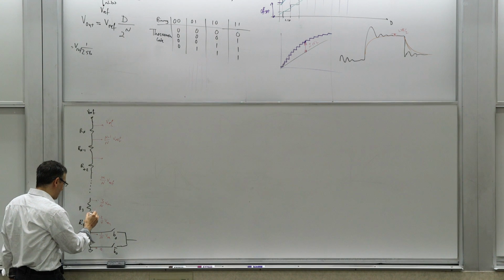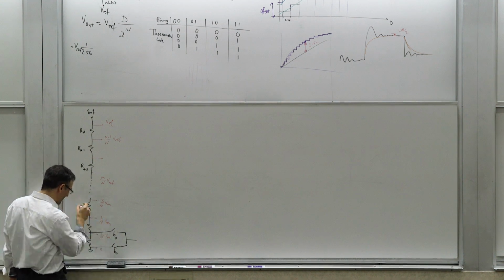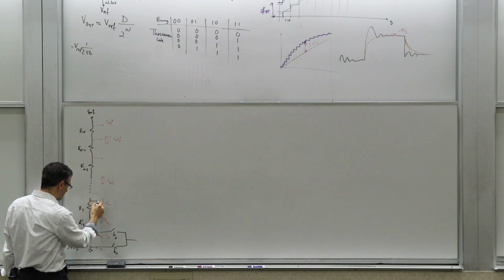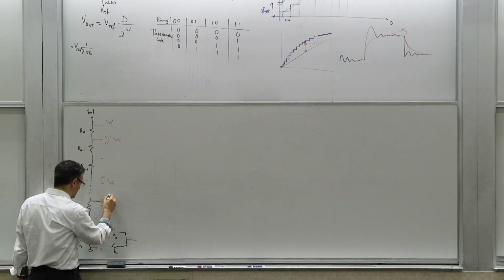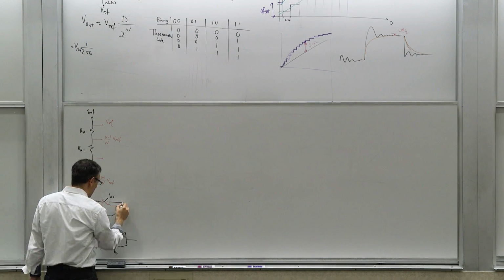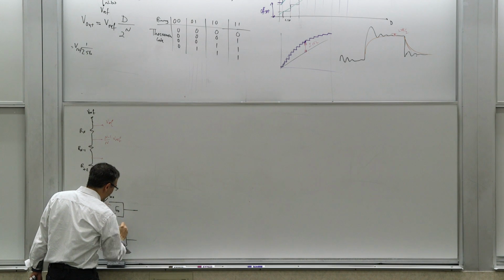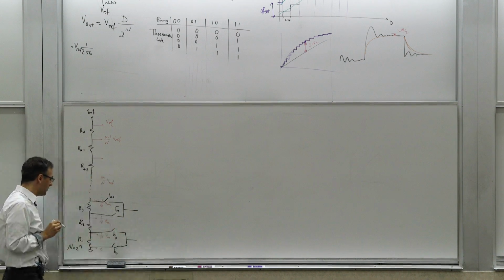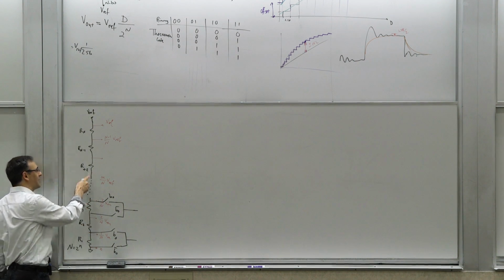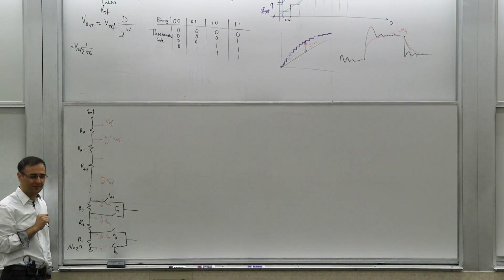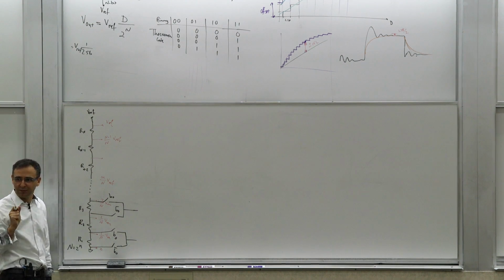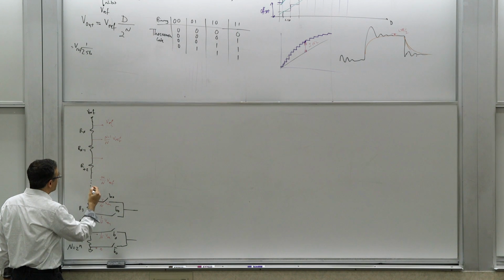Right? And we repeat doing this every other stage. B0, B1, it's going to be B0 bar. Because you remember, if the LSB, the lowest bit, is 0, you're either connected here, or you're connected here. You go every other one, right? This is not a great D2A, by the way, just what we're going to build. But let's make the simplest D2A first, right? And then you keep going the same way.